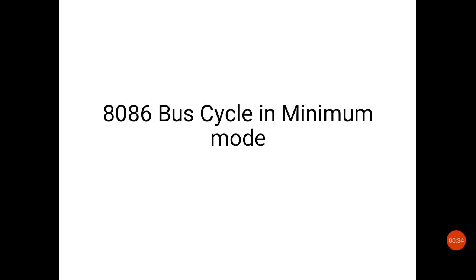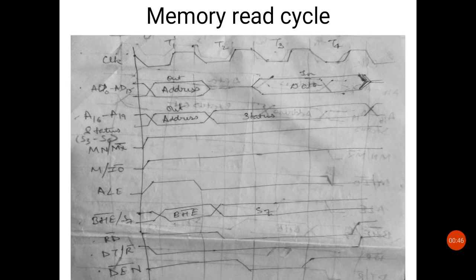The execution unit of the 8086 microprocessor executes instructions in certain clock periods. These clock cycles do not constitute any form of machine cycles. The bus interface unit of the microprocessor fetches instructions and operands from the memory, and any external access either to the memory or input-output device requires 4 clock periods. This group of 4 clock periods is called a bus cycle.